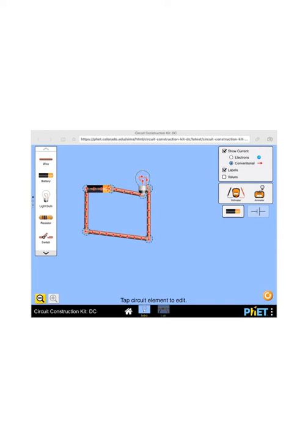Suppose that I wanted to measure the current in this system. I'm going to use an ammeter to measure current. I'm going to place my ammeter in this circuit somewhere that is capable of measuring current to intercept some of that current and record its value. I see that in this portion of the circuit, we read 0.15 amps. Along our battery, we read 0.15 amps. It really doesn't matter where I place this ammeter. I'm reading the same current all the way through.